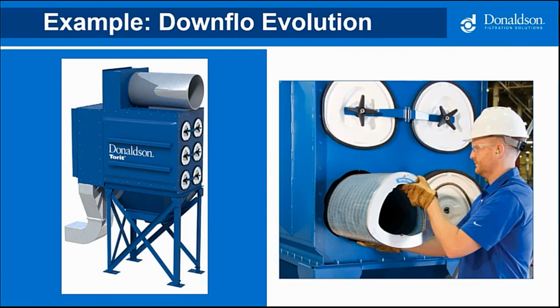The face you see here has a metal cap. You can see the gasket seal here. Well, there's another gasket on the other end, going to the tube sheet. So it's imperative that you put the filters in the right way. These can be removed without tools, or you can use the hex nut to take these out.